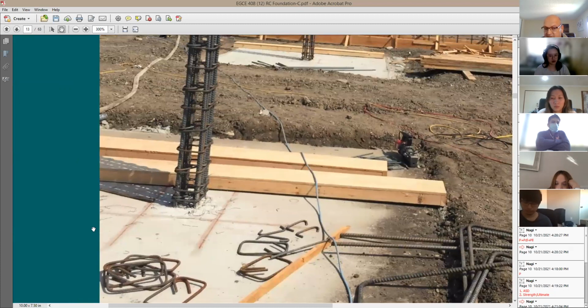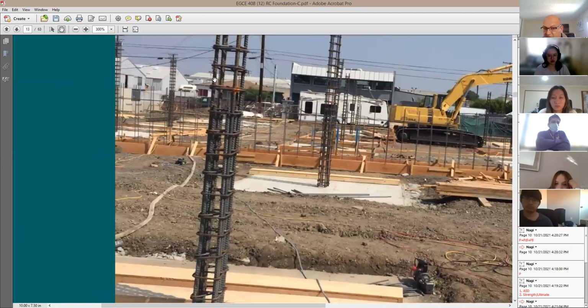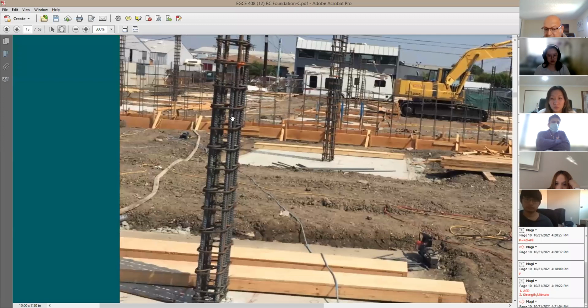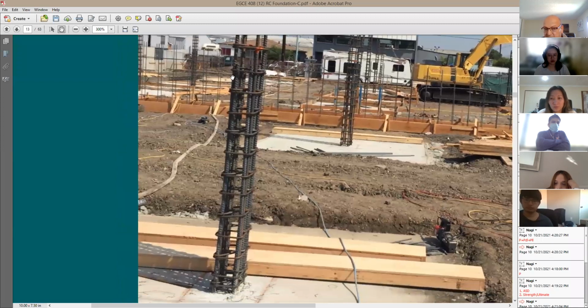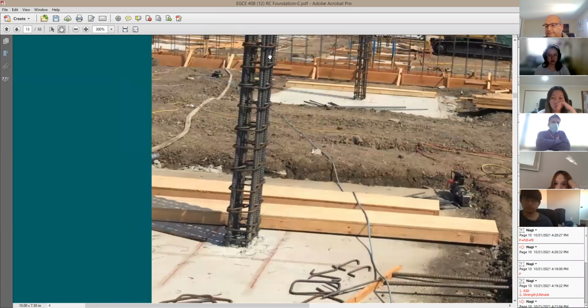They come here and make this mark on the concrete pad. This is going to be for the concrete column formwork. And here's the concrete column reinforcing, right? You see here, they start to add the vertical reinforcing that goes through the column. So this is what you hear called the splice. This is going to be the splice length from this point to that point. And you see, you have all the ties that I asked for. Now they're ready to put the formwork for the column.